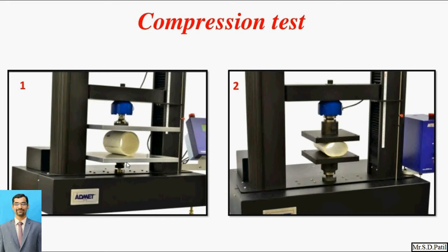Due to this, the compression test is mainly used to test brittle materials such as cast iron, concrete, stone, bricks and ceramic products. During the test, fracture occurs in a brittle material, and therefore the ultimate strength is determined corresponding to the fracture point, and no fracture occurs for ductile materials.